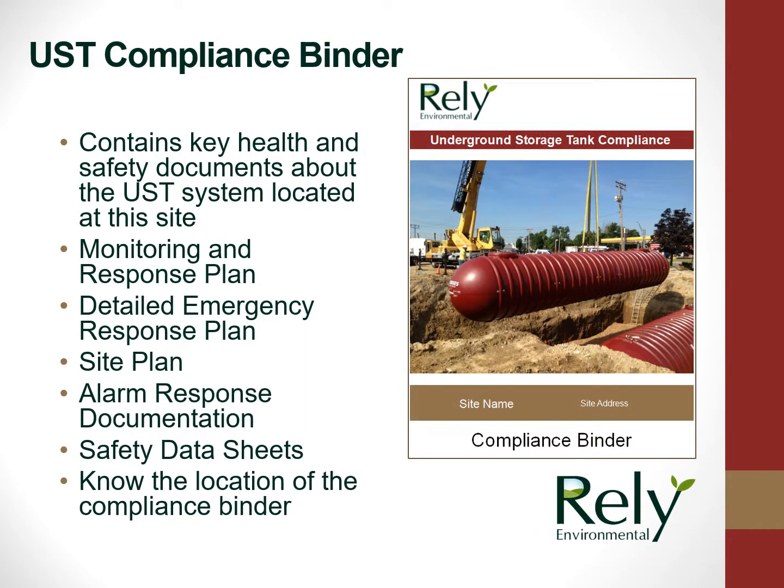Finally, there is the Underground Storage Tank Compliance Binder. It contains all the legally required compliance documents for the underground storage tank system. This includes permits, monthly designated operator reports, the monitoring and response plan, a detailed emergency response plan, the site plan, alarm response documentation, safety data sheets, formerly known as MSDSs, and records for the training you are completing today. Check with your facility and know the location of the compliance binder.